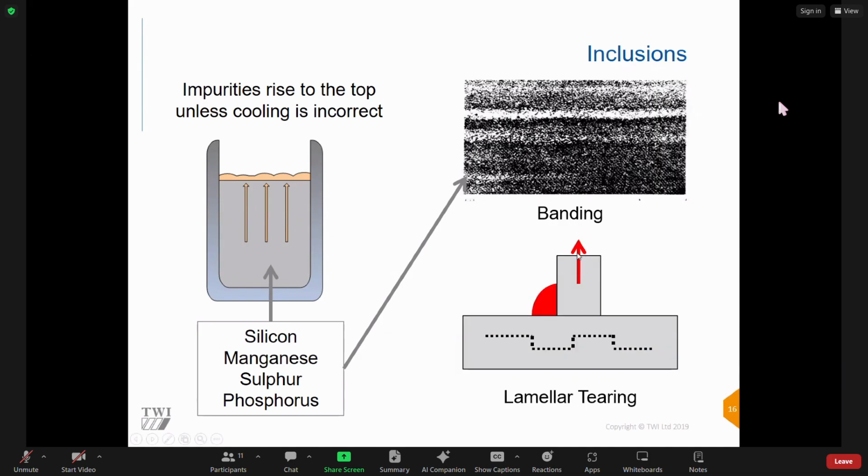These impurities, if we put a through thickness stress on our component, say a T-joint that is fillet welded, can then open up, and we'll get what's referred to as lamellar tearing. That crack would have a step-like appearance as it lines up with all those other defects. But again, not really something you need to be too concerned with. Next one though,